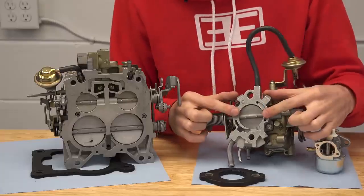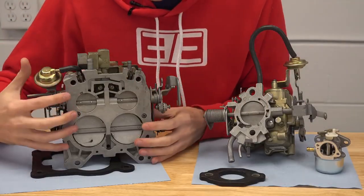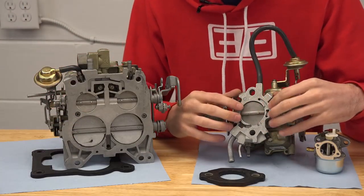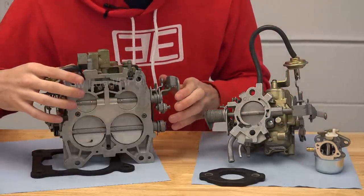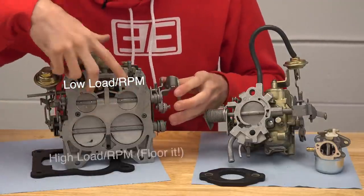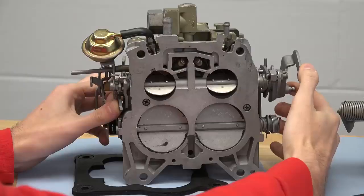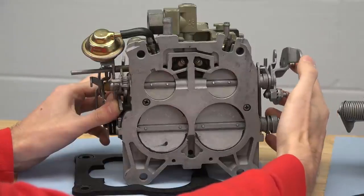So here you see a single barrel carb, and then here we have a 4-barrel. And what this allows you to do is operate in stages. Instead of just having one constant that has to maintain that air-fuel ratio for all of your engine RPM, you can tune things a bit differently so that when you're at lower RPM, you're just opening up these two smaller barrels, and then once you get up into a high RPM and you need maximum fuel flow and maximum airflow, you can open up all 4. And that will allow you to have a better range of air-fuel ratios that help the engine run smoother throughout its RPM regions.